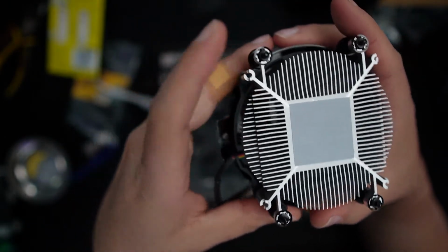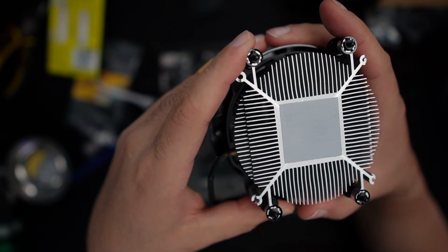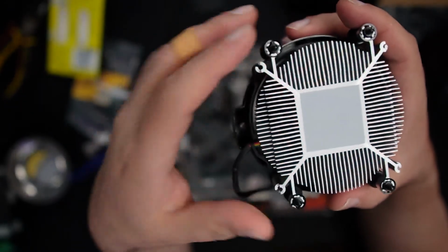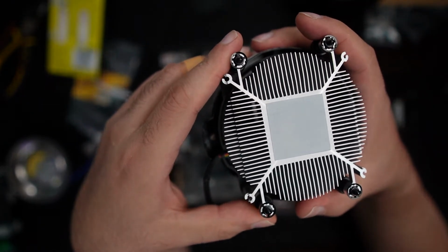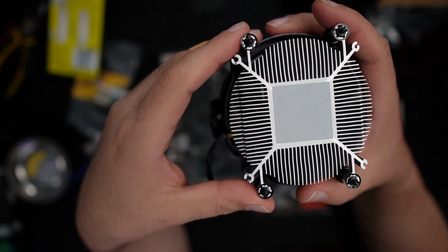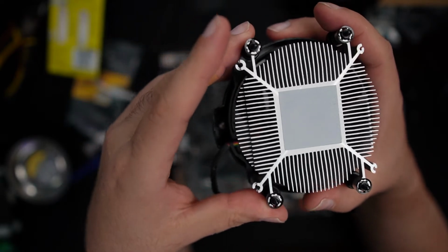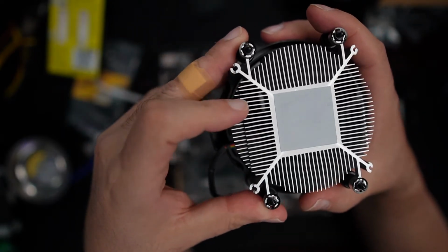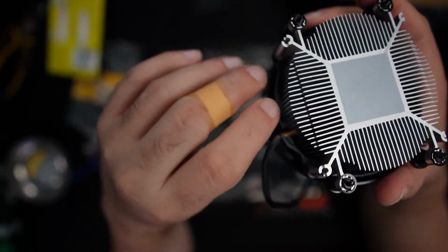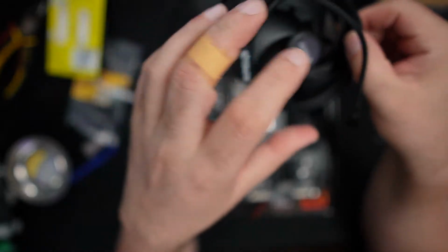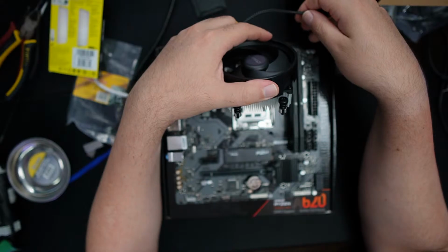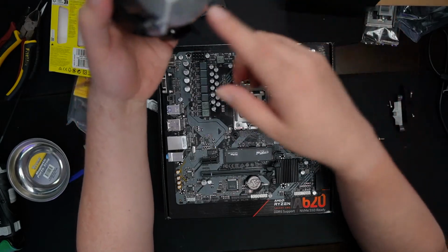At this point, that thermal paste should last a good few years before you have to reapply it, unless your system runs 24/7. If it does run 24/7, you may want to check it like 2 years in just to make sure everything is still good. Or if you're getting high temps, you may want to check it at that time and reapply new thermal paste and remove this thermal paste. We have other videos on how to remove thermal paste as well as reapply a new one. So if you want to check that out, you can check that out on our YouTube channel. And it does go over everything about reapplying thermal paste, adding new thermal paste, making sure that you don't mix and match thermal paste.